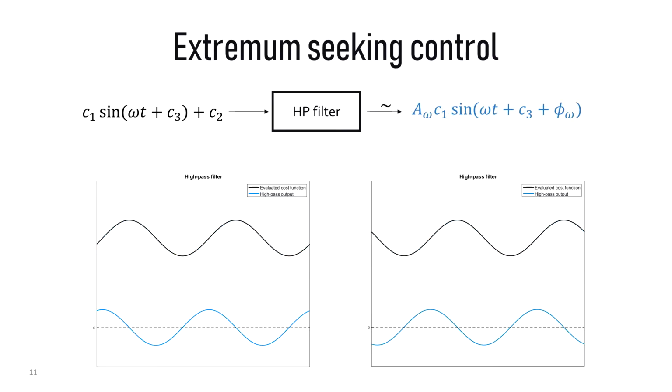We can take the response, shown in black, and apply high-pass filtering to end up with a wave that oscillates around zero. The filter can add a lot of phase delay, but the amount is known since the filter is linear and we can compute phasing for each frequency.